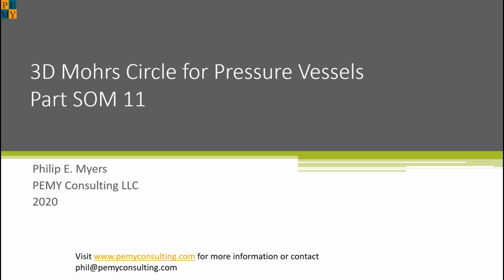The easiest way to understand how the maximum 2D plane stress can be exceeded, which is called the absolute maximum shearing stress, is with a so-called 3D Mohr circle. Even though it's called 3D, it's really just 3 rotations about the 3 axes and the 3 resulting 2D Mohr circles. I'll show you what I mean next.